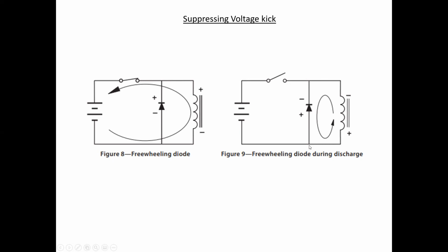We'll put diodes in places where that inductive kick could cause damage to electrical equipment. And a really good example of that is when we have DC relays that are used along with PLCs, or programmable logic controllers. A PLC is very expensive, and when we are controlling a DC coil of a relay with a PLC card, we don't want the inductive kick to fry the PLC card when it energizes and de-energizes the DC coil. So you'll see that quite often.